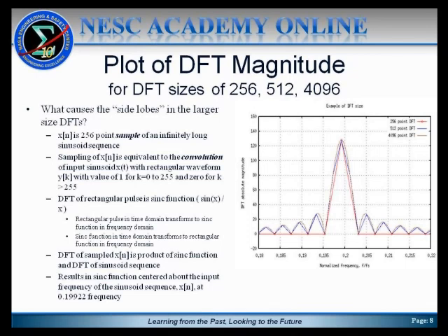What you can see from that is the discrete Fourier transform of a rectangular pulse results in a sinc function. That can be shown from just the material that was presented in part 1: you pass a rectangular pulse through it, you'll get a sinc function out, which looks in the time domain like sine x over x, or sine t over t if x represents time. A rectangular pulse in the time domain would transform via Fourier transforms into a sinc function in the frequency domain. Conversely, if you started out with a sinc function in the time domain and did a Fourier transform of it, it would transform to a rectangular function in the frequency domain.